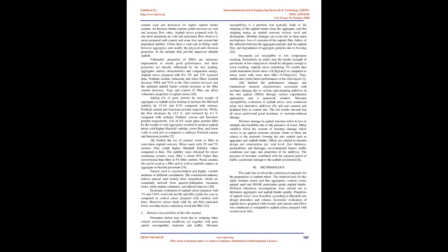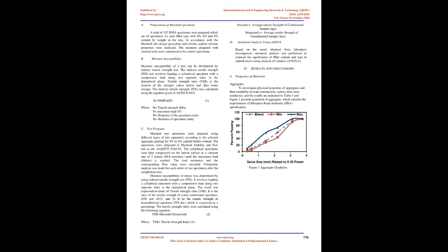From the considerations of performance, economy, and availability, waste concrete dust and brick dust are suitable as filler as compared with conventional filler. 15. The application of brick dust as filler material had a significant effect on the physical properties of hot mix asphalt. Using brick dust as filler made the asphalt mixes with higher Marshall stability, lower flow, and minimum voids filled with asphalt. Hence, brick dust can replace conventional filler, stone dust and cement, in the asphalt paving mix as control material. 16. 17.